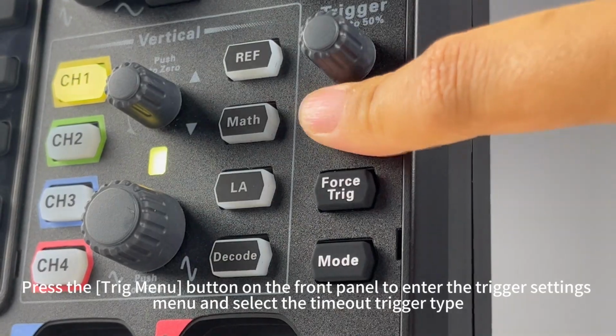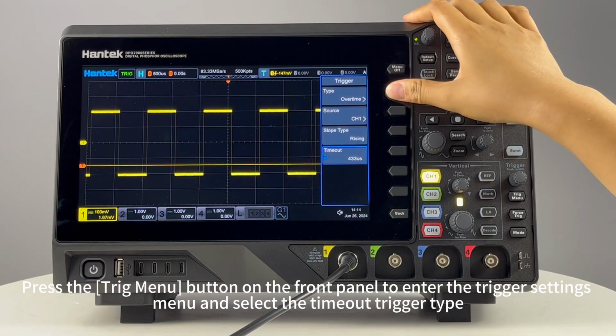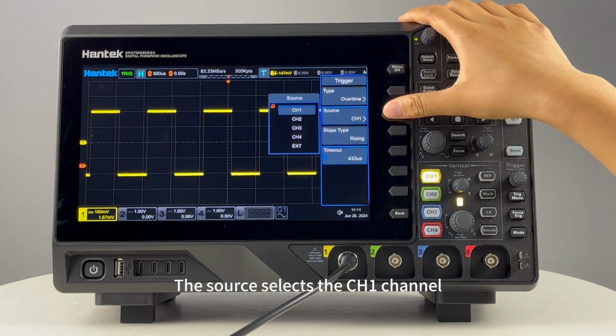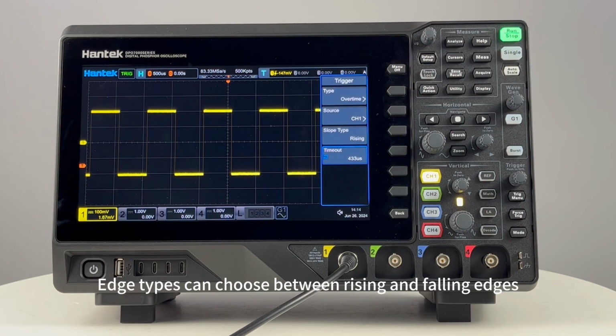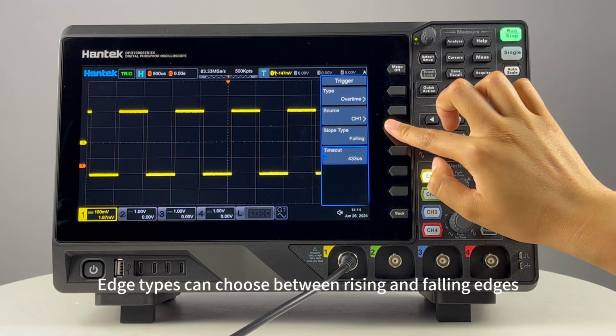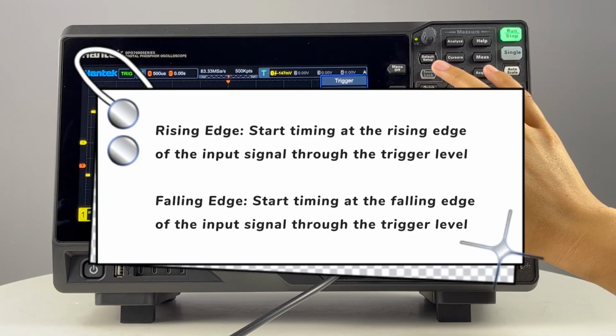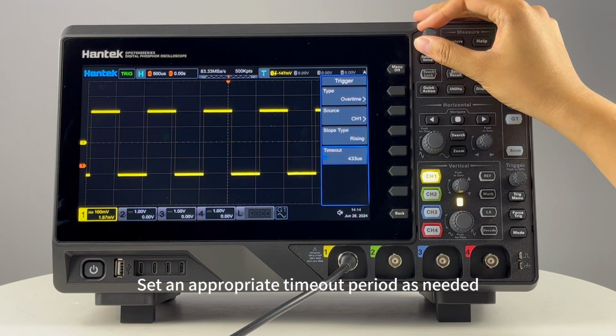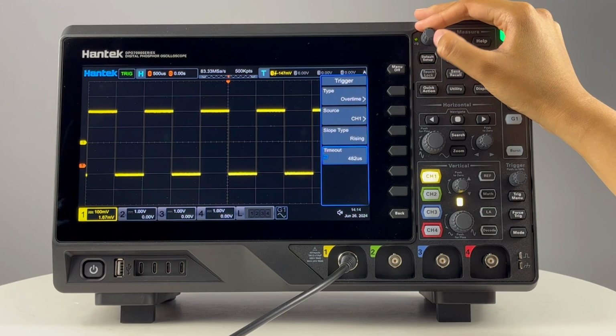Press the Trig menu button on the front panel to enter the trigger settings menu and select the timeout trigger type. The source selects the CH1 channel. Edge types can choose between rising and falling edges. Rising edge: start timing at the rising edge of the input signal through the trigger level. Falling edge: start timing at the falling edge of the input signal through the trigger level. Set an appropriate timeout period as needed.